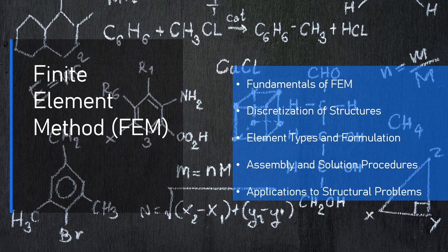Benefits: ability to model arbitrary shapes and boundary conditions, e.g., simply supported or clamped edges. Can account for bending, shear, and membrane forces in a single solution. Enables detailed analysis of stress concentrations around holes, cutouts, or discontinuities.